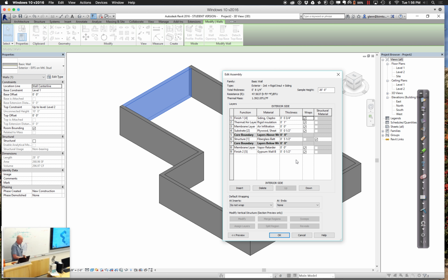Okay, you'll see that actually made a huge difference. This wall was like an R70 some odd prior, and now it's an R47, which is probably a lot more realistic. So that 1 inch of rigid insulation is actually raising it. It's actually not too awfully bad. If I needed to have a thicker, more insulative wall, I could raise that to maybe more rigid insulation. Or I could take that out if I didn't need that so much. That's an R51 wall.